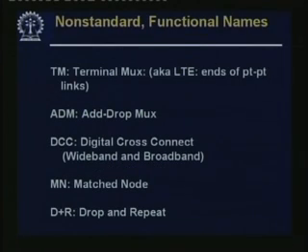Then there are some non-standard or functional names in SONET, like TM for terminal multiplexer, also known as line terminating equipment or LTE. So, these end point to point links. ADM for add drop multiplexer, we have mentioned this. DCC for digital cross connect, wideband and broadband, we have mentioned this also. MNR for matched nodes, and D plus R means drop and repeat, etc. Anyway, these are just some terms.